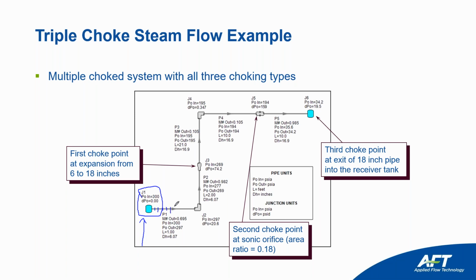As we march down the pipe, we calculate all the pressures, temperatures, velocities, etc. We are making sure that the mass balances, momentum balances, and energy balances at each computation station along the pipe as we march along. Then we round the elbow here and we keep marching along down the pipe.